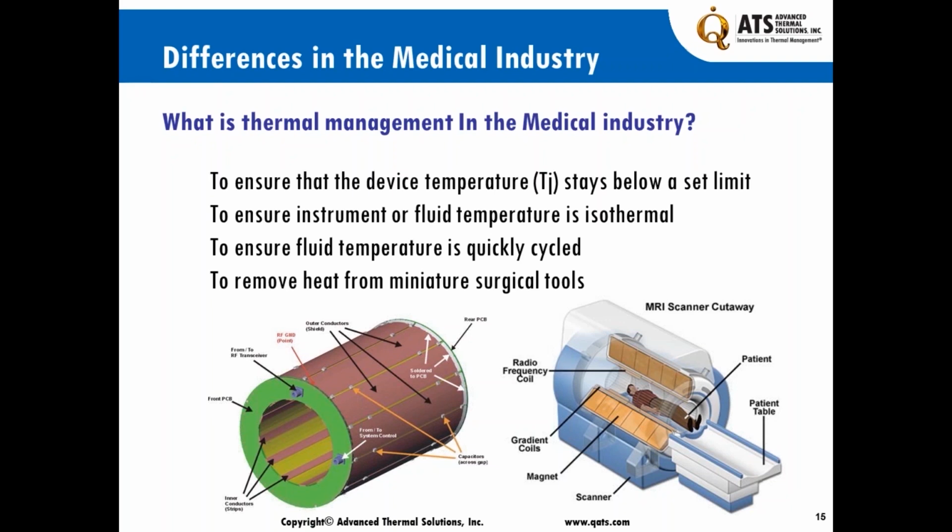And one of the big issues, for instance, in an imaging system, is the system being isothermal. You're talking about something like 2.5 meters with half a degree C as the requirement for temperature to be isothermal. These are major challenges that our brothers and sisters, the mechanical engineers in these companies, are working with in order to make sure that these criteria that I've listed here are met on a regular basis.